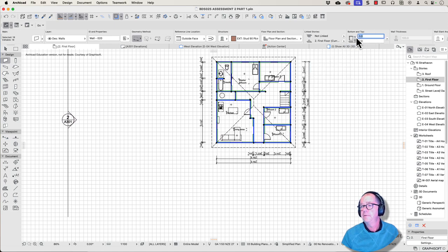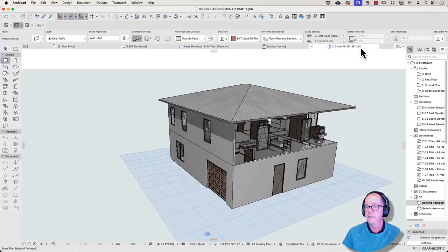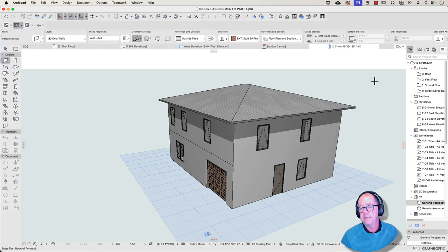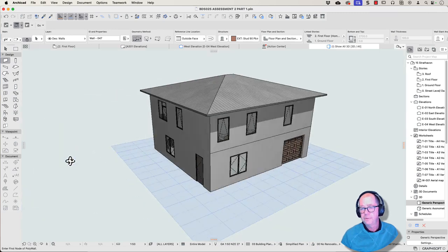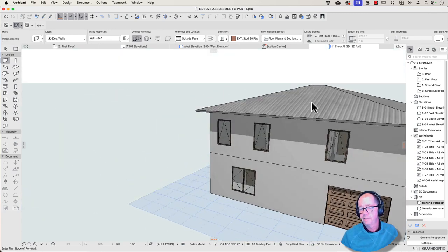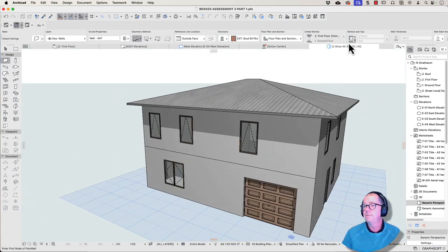and then we can change the elevation, 2700, and that should correct all of the walls. Let's have a look in 3D. So now you notice that it's updated, and I now have my complete building with all of the walls at the correct height and all the stories correctly located. Changing the floor to floor height also will change the stairs that are connected between the stories.